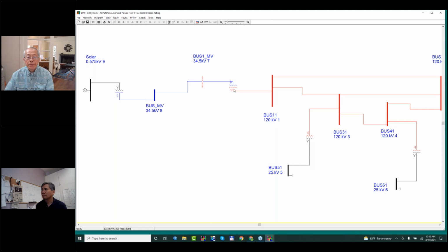And on this side, you can also avoid doing this shunt if you use the Y-delta transformer, okay, with the delta again connected to the generator side. So this is how important it is that you set this up. And now let me open the dialog box for this type 4 wind machine for you to look at real quickly in case you haven't seen one yet.